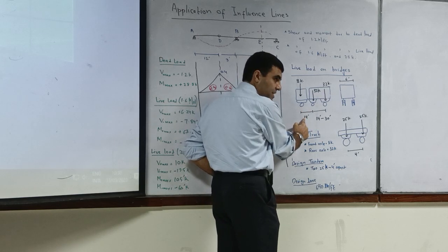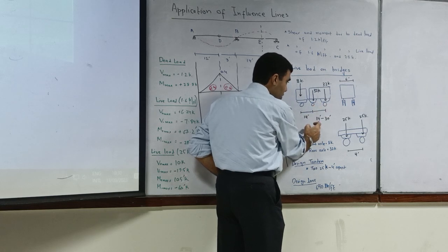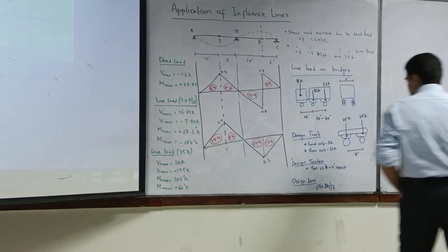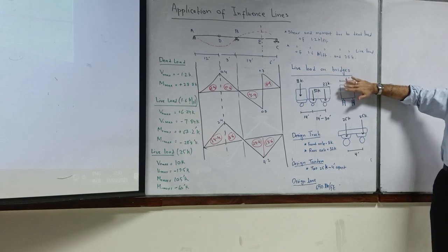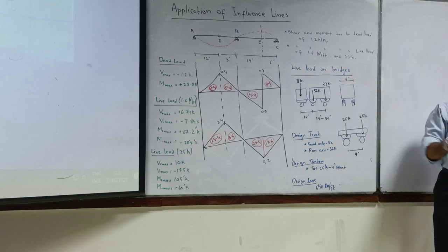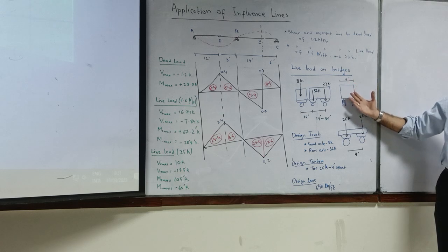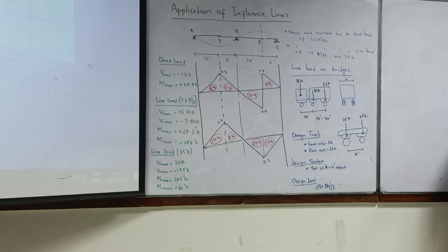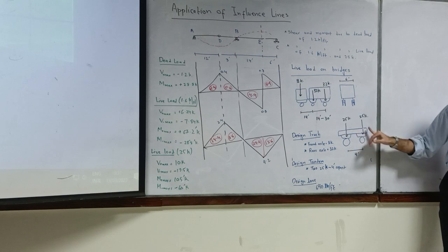Between the front axle and the rear axle is 14 feet, and between the two rear axles the distance is 14 to 30 feet. Then after that you can have a tandem attached behind it, with a hook or something, another two axles, and you can place more load on it. That is called a tandem, and it is normally considered 25 kip.